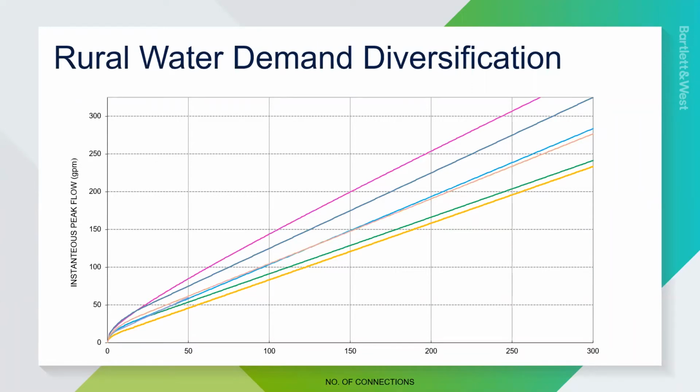Another factor with developing these curves is cost, obviously, and density. So if you were to design a pipeline and you had largely dense urban sprawl areas, it would be more cost effective or easier to maybe give those residents a higher demand curve, as opposed to areas where they may be sparsely populated in largely rural areas. And in that case, it may only be feasible to bring them a certain amount of water, and so then you would have a lower curve in that type of system.